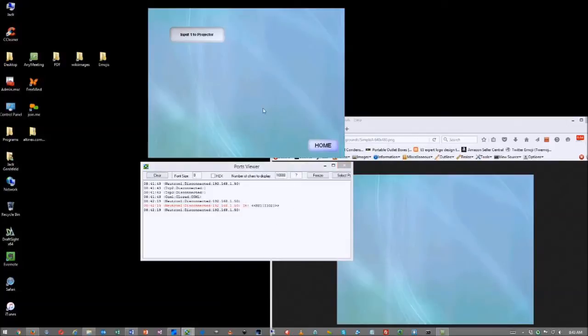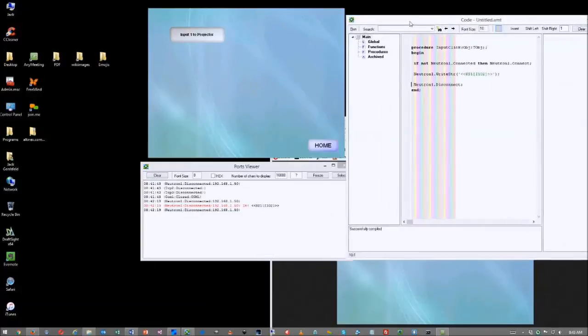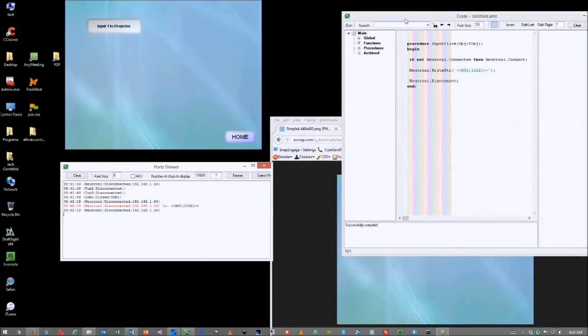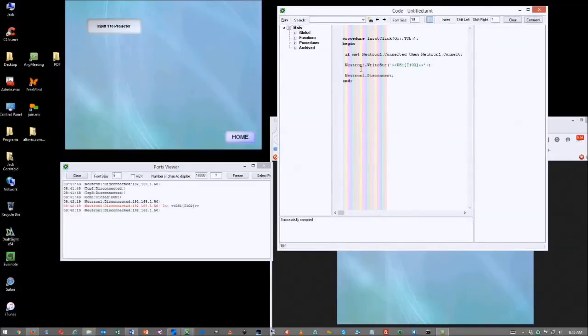So you can see between this and pressing F11, in a development mode, when you're actually working on this, trying to get the program going, you have all the views available, and you can see what's going on. So I'm going to put a check mark right here, which is the point where I want to stop. And then I'm going to come back here and press the button. As you can see, as soon as I press the button, it stopped right here. It said red, and it says, I'm right here, but I'm not going anywhere until you do something else.